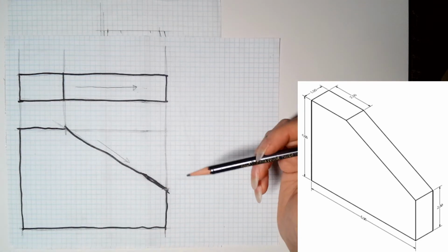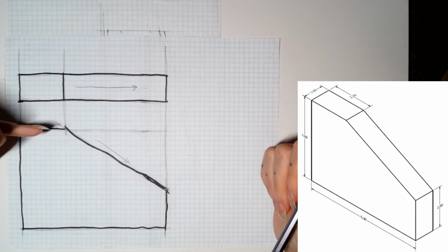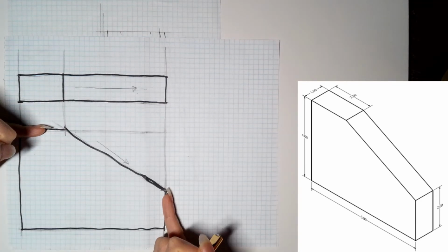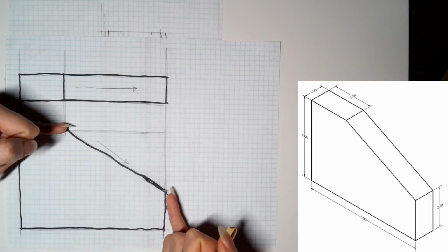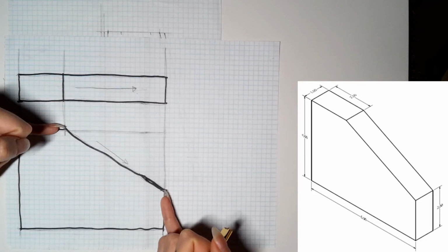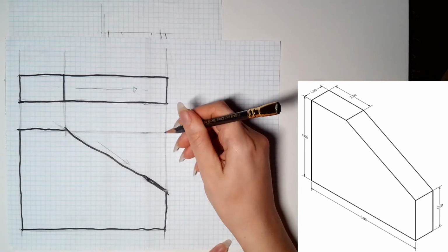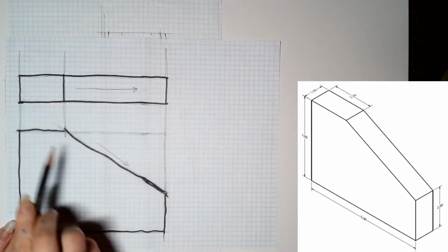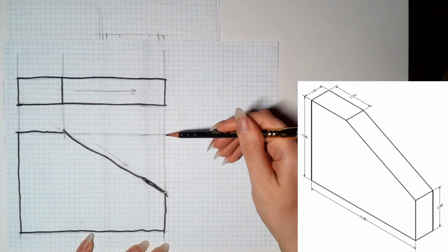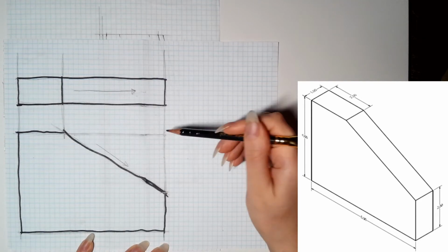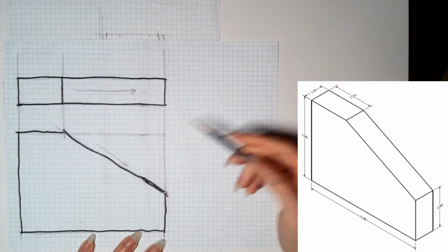Where you want to draw it is from where your topmost and rightmost lines of the front view meet. So in a lot of cases, it's directly on the object. In this case, it would be right here because it's where the topmost and rightmost lines meet. That isn't directly on my object, but that's still where I would do my miter line.